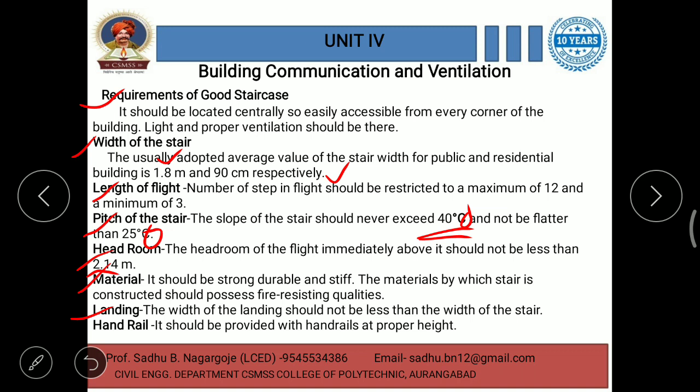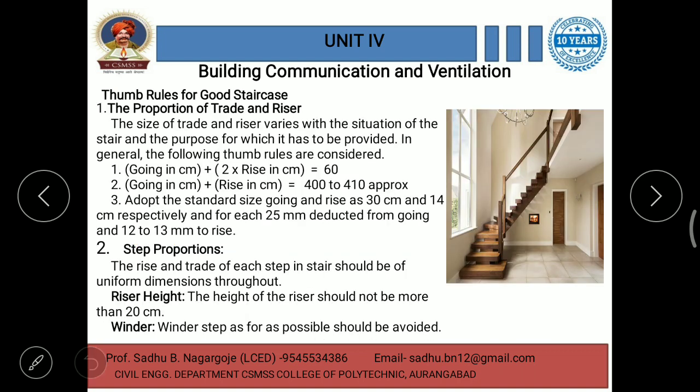At least the width of the landing should be the same as that of the stair. Landing means the portion at which we change the flight. That portion is the landing. Handrail: it should be provided with handrails at proper height.